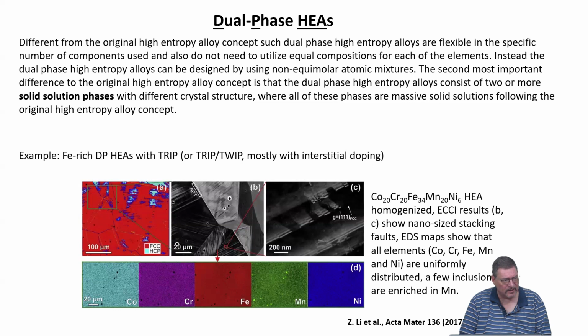Obviously, microstructure gets more complex, right? Because basically you have now different phases, and the phase content also depends on your processing conditions. So if you deformed it heavily, then basically you undergo also some of these transformation-induced processes. And so it means that you need to account for their reversal by, for example, temperature exposure for a longer time.